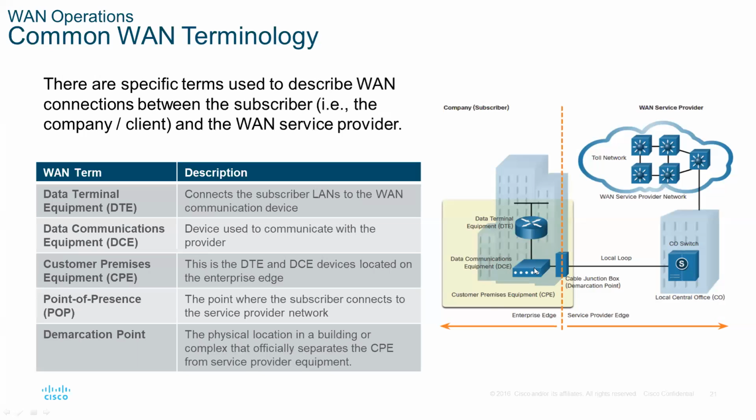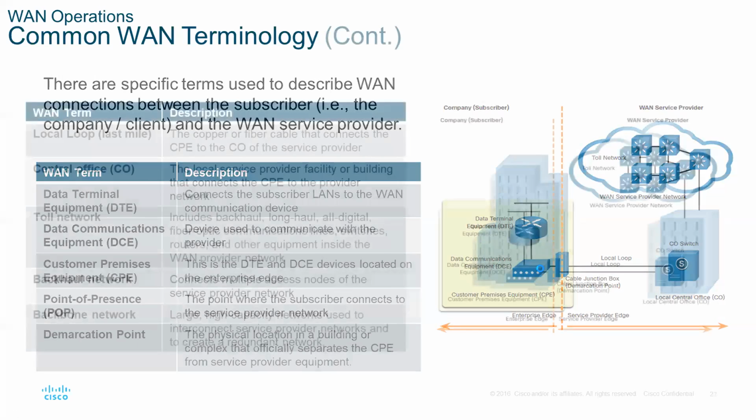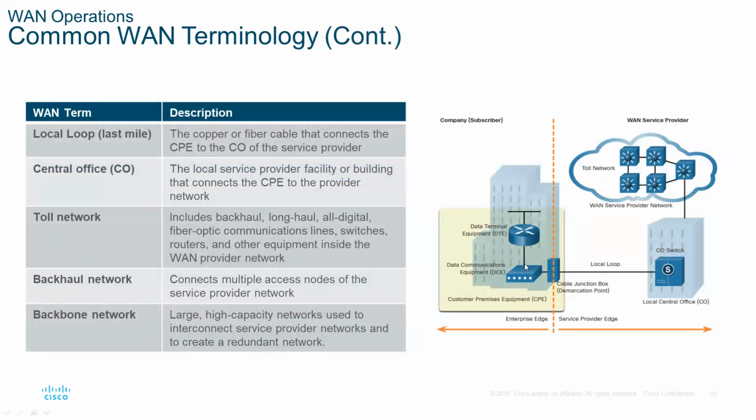So when we talk about cables and DTE and DCE ends, generally speaking, we have termination equipment here, and we have customer terminating equipment there. And the cable between has to have specific connectors to terminate against the DCE and the DTE. Generally speaking, the DCE controls the synchronization between these two devices as far as timing of the signal.